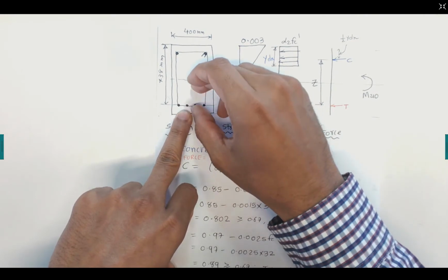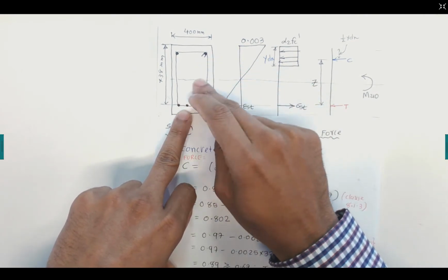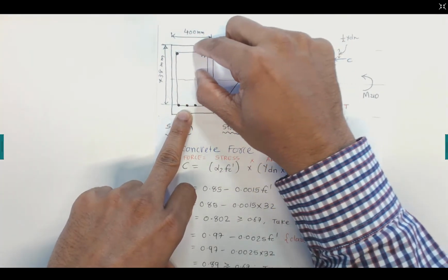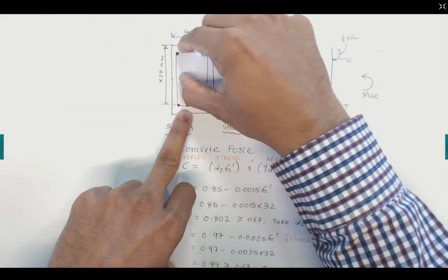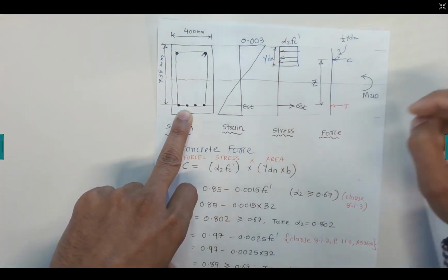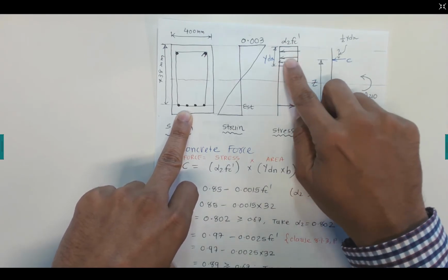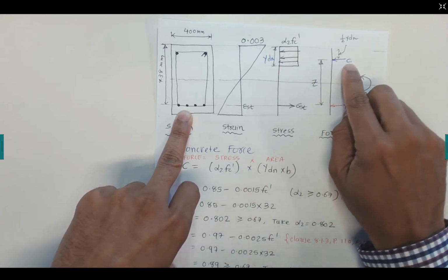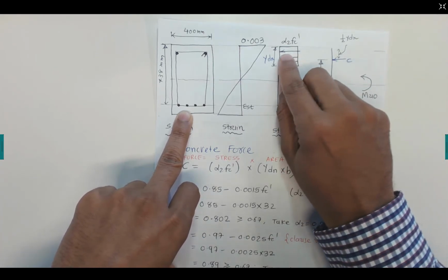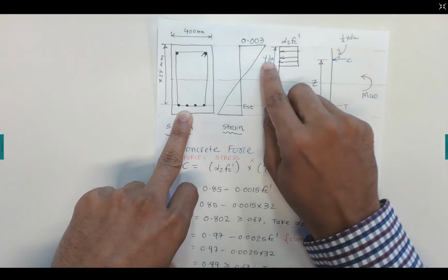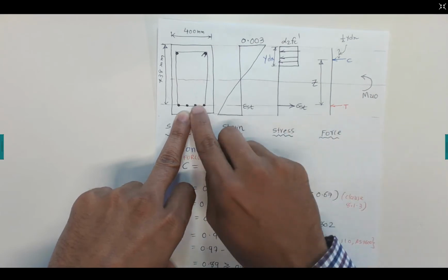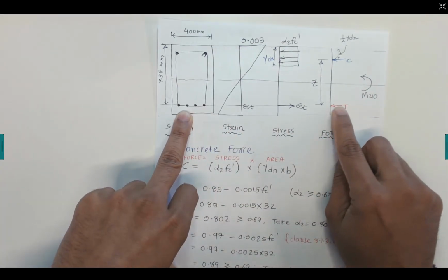Concrete below the neutral axis is subjected to tension, so there are no forces considered in this region. There are compression forces, not taking the whole portion but just the average of these effective stresses here. Now if I take this whole distribution as one force, that is the compression force in the concrete, it should be applied at the center of this length, which is half of gamma dn. And similarly we have the tensile force in the steel bars, which is applied here.